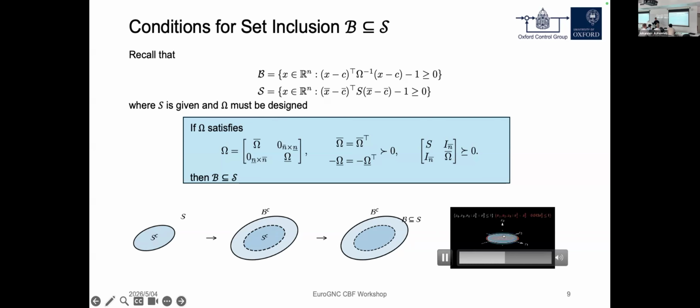This is the subspace for the obstacle, and this red set is the control invariant set, the projection. We expand it into the original space, the R^n state space. The obstacle will be a cylinder in this case, because you expand from an ellipsoid to a higher dimensional space. In the function we design, the first block is positive definite and the next block is negative definite, so it would be a hyperbolic, which covers the obstacle on the state space.